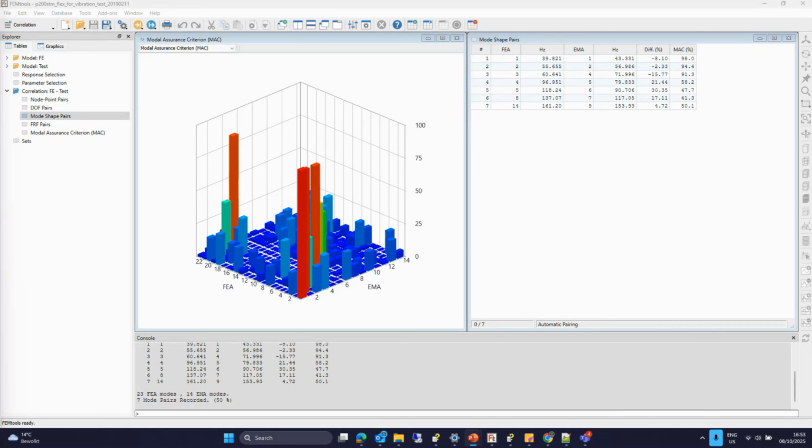That's Nastran terminology for the binary results files. These OP2 files are automatically created if you add the parameter POST -5 in your Nastran bulk data. So -5 is a code that's specific for FEMtools, which will instruct Nastran to produce the necessary output2 files.